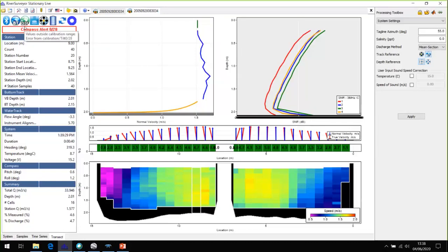And it's really useful in low velocities when there might be a wind blowing the platform around underneath the cableway and it's drifting about, or sometimes a remote control boat when you know you don't have a moving bed but you still want to use this method. It's useful as well if maybe your boat's rotating a bit.